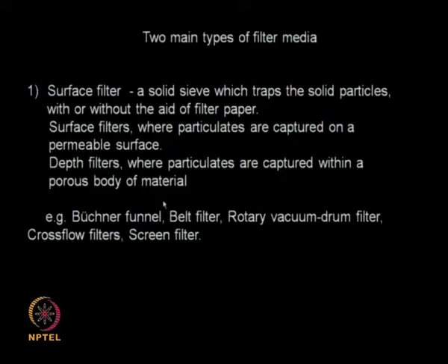So the depth filter will have several layers of material which captures the solid which you need to filter. So surface filters can be Buchner funnel, which we use in our lab, belt filters, rotary vacuum drum filter, we looked at it in detail some time back, then crossflow filters, screen filters and so on actually.